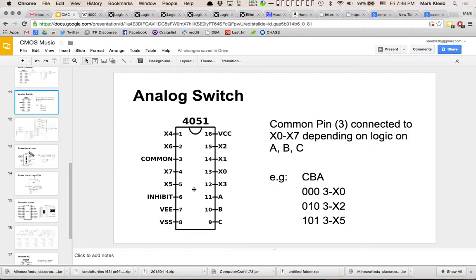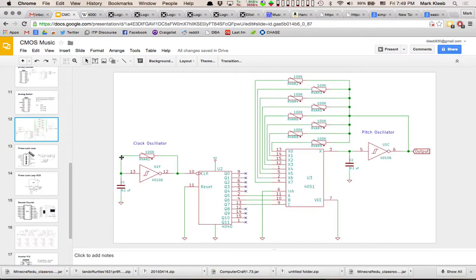I was curious if that's a convention of Eagle or whatever. So Eagle actually has two distinct parts, right? There's the schematic and there's the board. So when you're placing parts, there's actually two diagrams associated with it. There's the diagram that you would see in something like this when you're drawing your circuit. And then when you convert it to a board view, that's when you'll have the actual pin layouts for placing the parts down. I'll show you those too, and they actually tie together really nicely. All right.